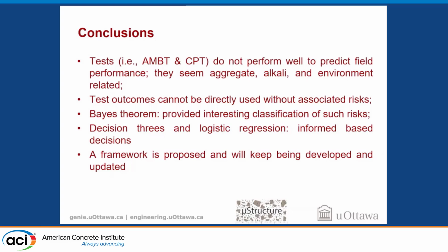What we actually didn't know is how bad they were, and they look very bad number-wise, and they could be even worse, again, if I was using aggregates that, in quotes, do not behave well. I only used aggregates that are very well calibrated, where everybody knew their performance and so on. Whenever we change mineralogy and start using aggregates that are the so-called slowly reactive aggregates, granites, for instance, things might be way worse than this.